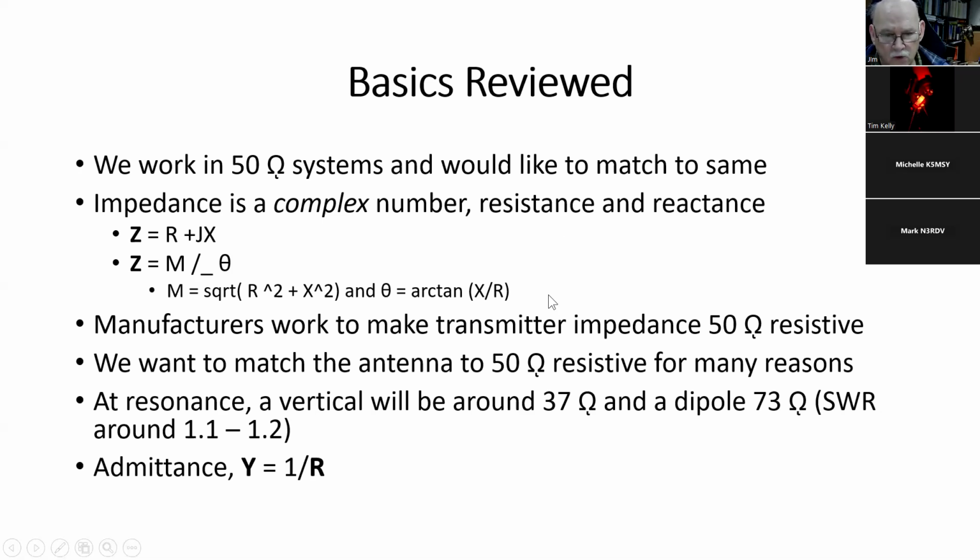Why express it two ways? Well, in my days at the Naval Academy with an HP calculator, you can add impedances with R plus jX very easily, but if you want to multiply or divide, the angular expression becomes easier because you just multiply or divide the magnitude and then add or subtract the angle. So there are reasons for both.